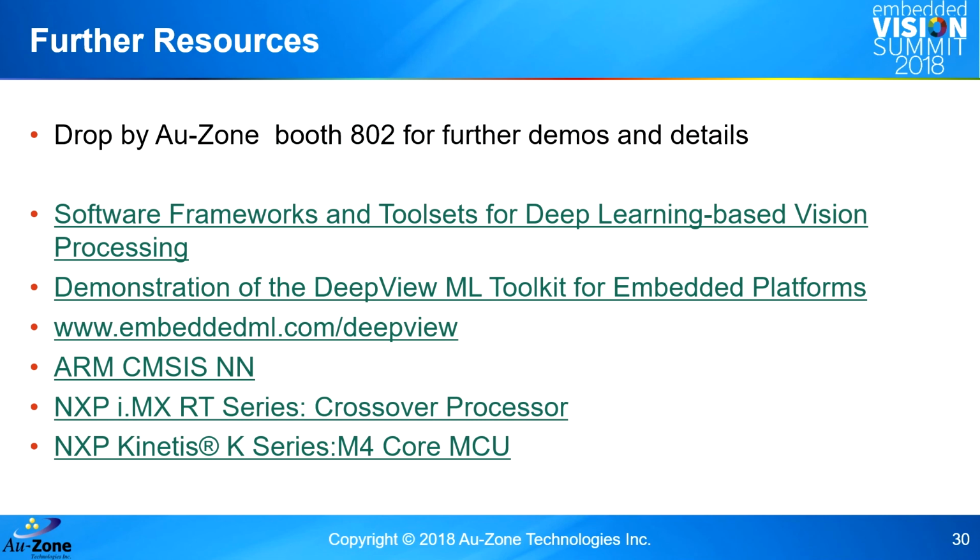Great presentation. If you could add one piece of hardware accelerator to your microcontroller, what would it be? Tightly coupled memory is probably number one. So often these devices are not so much CPU bound as they are memory interface bound. So we found significant improvements with tightly coupled memory. Now, going beyond that, an efficient matrix multiply hardware is probably the next key piece.